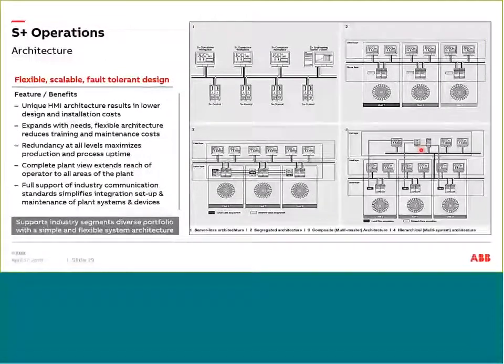The other thing that we have done, especially when we are migrating over from legacy consoles, be it PC View or be it Conductor NT, is that you can mimic the same architecture. So if your operators or maintenance staff are used to having a certain architecture with a tag database split, you can do the same thing with Symphony Plus operations. So you're not introducing something new in terms of the architecture. And that flexibility is extremely powerful for us when we go in for integrating the plant automation system.